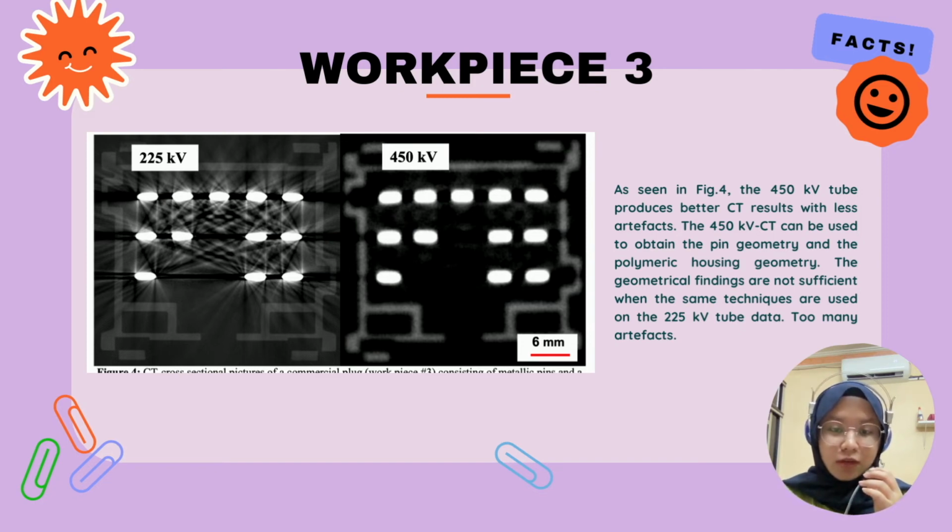Because of the strength of these artifacts, the polymeric material in the vicinity of the metal pins cannot be defined or examined using CT scanning. This is owing to the extremely different attenuation coefficients of copper and polymer, which result in a dynamic range greater than the detector's dynamic range. As we can observe on the right hand side in this figure, the CT results obtained with the 450 kV tube are far better and the artifacts are significantly reduced.